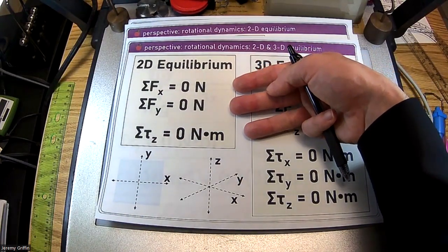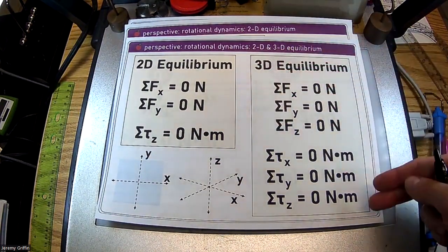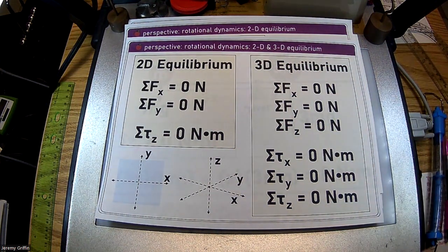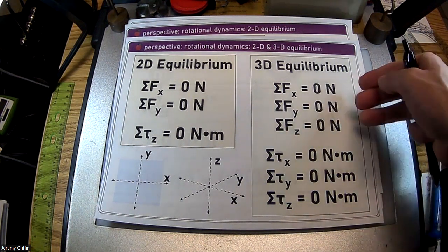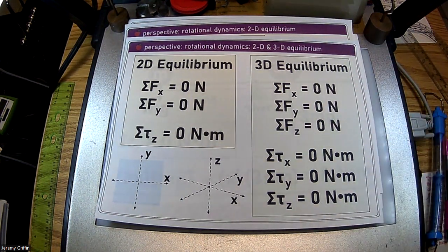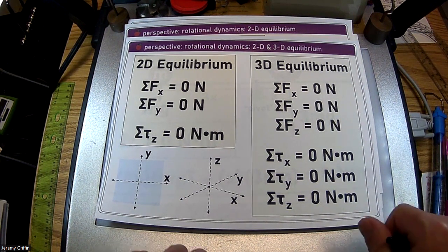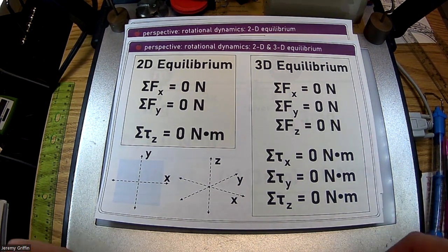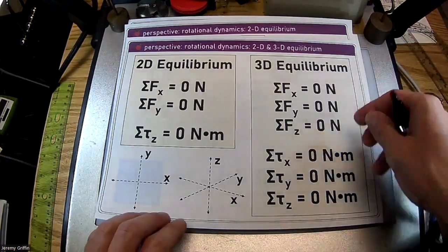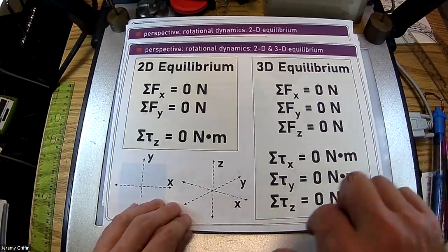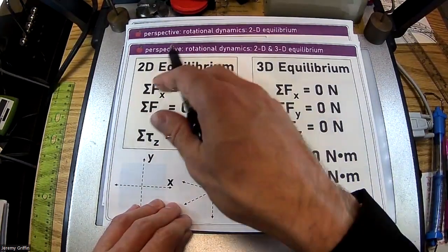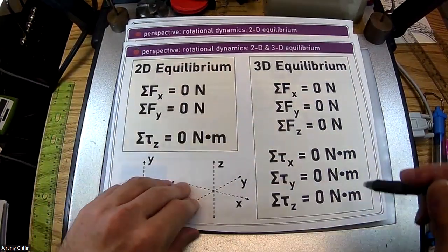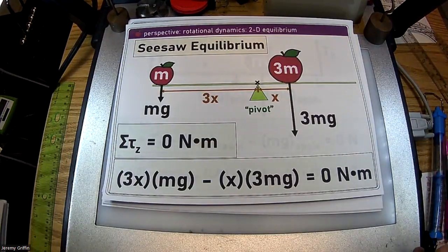Boom, boom, boom. Okay? If you opened this up to 3 dimensions, now you've got 6 equations, a 6 equation system. If you're doing civil engineering, designing a building, designing a bridge, some truss structure, you need to check all 6 of these conditions to make sure that they'll make static equilibrium. Then make sure your materials have the correct strength and correct diameter. There you go. In this class, we'll mostly stick to 2 dimensions, some kind of plane going on. But in a bigger context, if you're an engineer one day, you think about 3 dimensions.